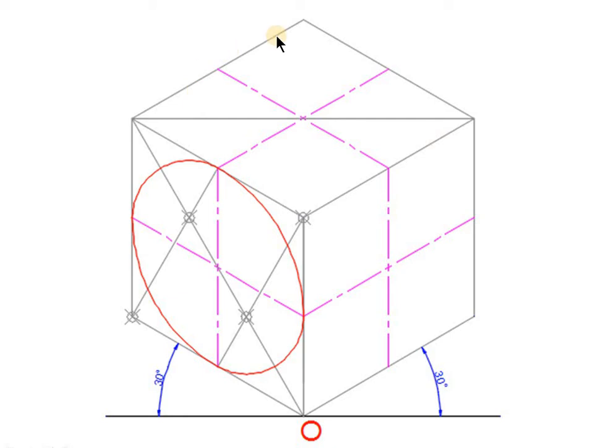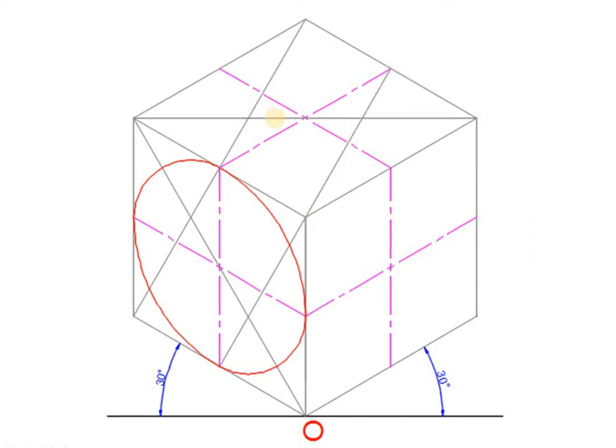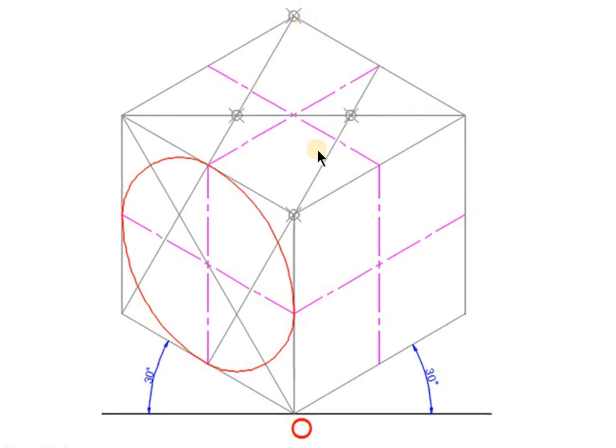Then as usual, this is a parallelogram, and our first step is to draw the longest diagonal. You are connecting the longest diagonal with the help of these 2 corners. After joining this longest diagonal, the number of corners left is one, this, and this is the second one. Okay, so from these corners you are bisecting the sides. So from here I am bisecting like this, and then from this corner I am bisecting the line like this. Okay, so you will see this way we have connected the opposite corners, and then based on this you got 4 centers. One is here, one is here, one is here, and one is here, like this.